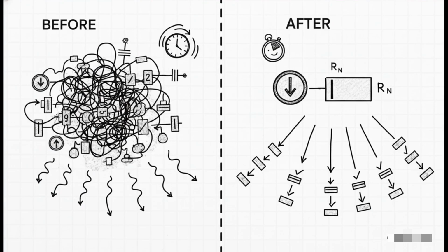I mean, think about it like this. Say you're designing an amplifier, and you want to test how it works with 10 different speakers. Without this theorem, you'd be stuck doing 10 separate, really complex calculations. But with it, you just create one super simple model of your amplifier, and then you can plug and chug the numbers for each speaker in seconds. It saves a ton of time, and believe me, it slashes the chances of making a simple mistake.